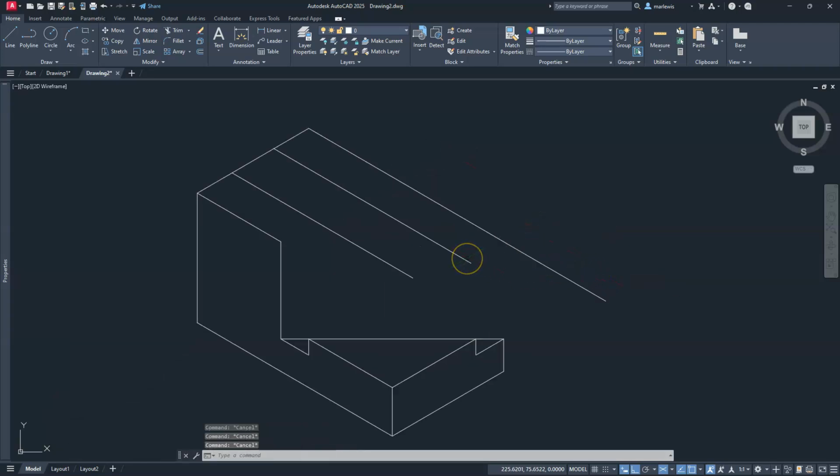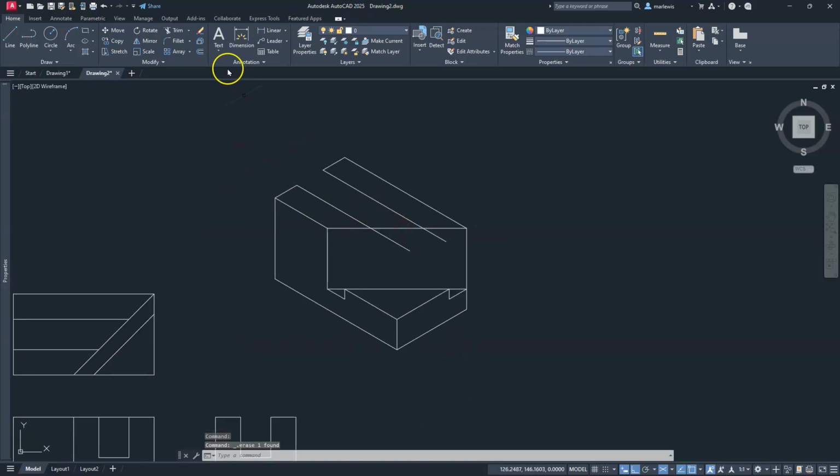Okay, so next what I need to do is I'm going to use the fillet command. Remember that my radius is already set to 0, and I'm just going to select this line here. I want to select that side of the line I want to keep, and then this side, right? Next, I'm going to start with the line, and I'm just going to go from this endpoint directly to that endpoint. So this is what I was meaning before. I don't know exactly how far that goes, but I'm going to go ahead and delete that line there in the back. I'm going to trim off this in the front here. So I'm just going to trim here, and also between here.